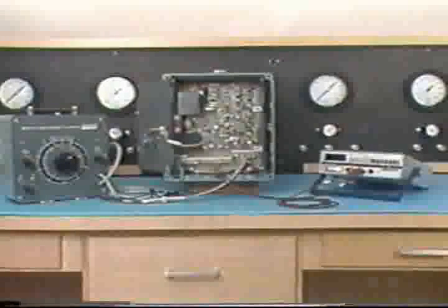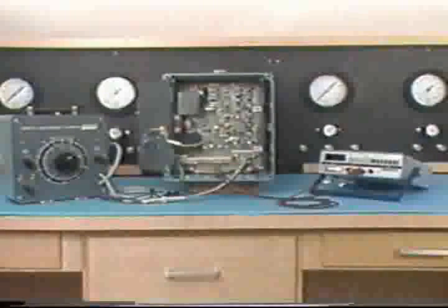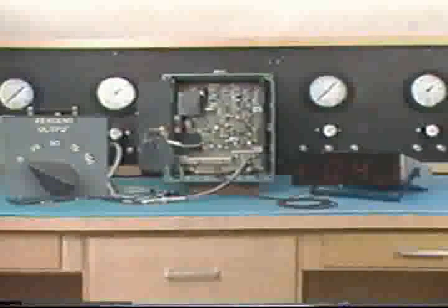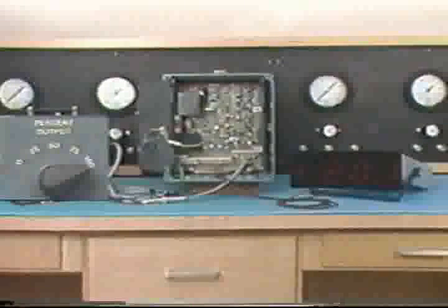Once the input standard is properly set, the instrument is ready to be tested. The magnetic flow meter calibrator here has predetermined test points. The first reading, taken at 0%, produces an output of 4.1 milliamps. At the 25% setting, the output produced is 8.1 milliamps. When the percent output switch is set at 50, the output produced is 12.1 milliamps. At the 75% setting, the output is 16.1 milliamps. The last reading in the upscale 5-point check is at 100%. The output produced is 20.1 milliamps.